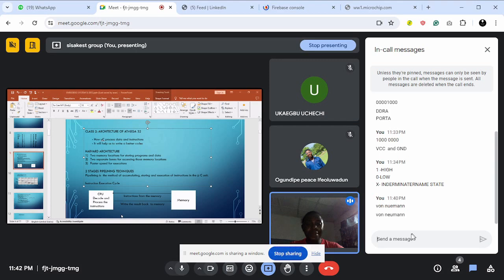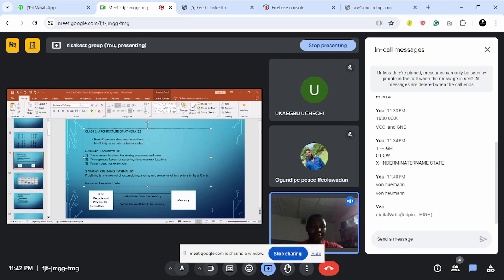Now, if you're writing on Arduino IDE, most likely you'll be seeing something like this. I'm just writing a typical code on my screen now. So I want to share this. If you write something like this on Arduino IDE, I believe my screen is also seen. You write digitalWrite with a pin. What this instruction is doing is turning on a particular GPIO pin.